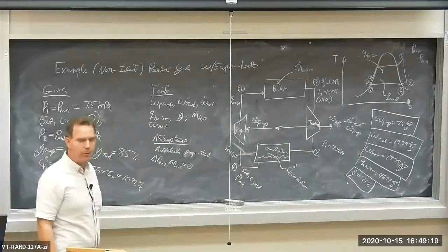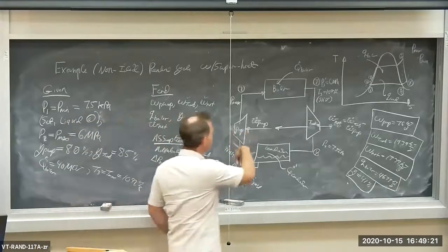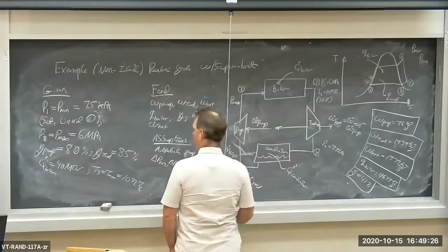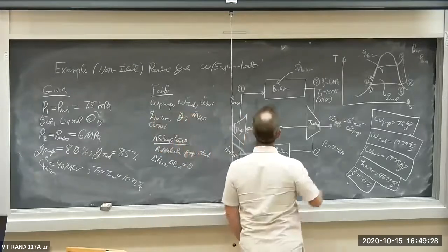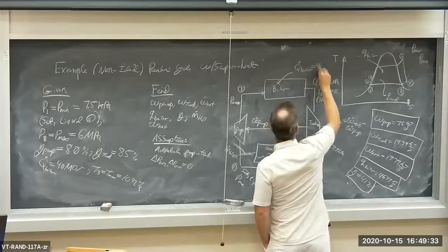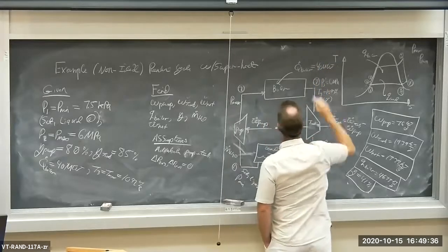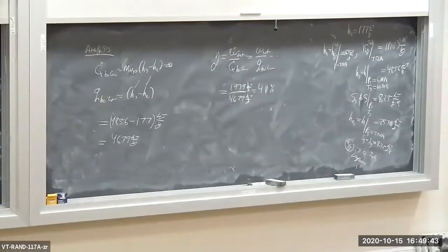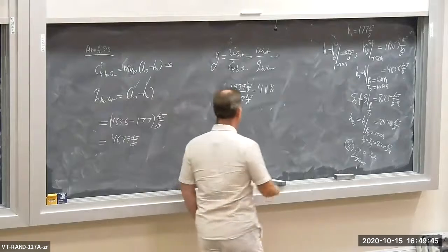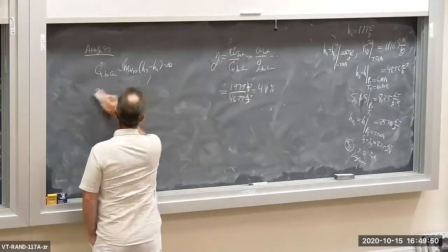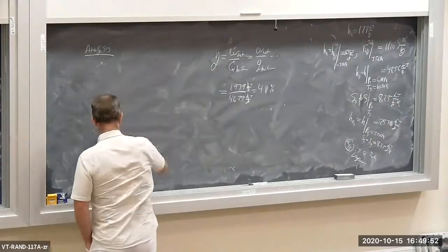Let's calculate the mass flow rate of the working fluid, the H2O, as it rolls around the system. Now, one thing I am provided here, it's simply given, but I should write it right here. The rate of heat addition to the boiler is actually 40 megawatts. Well, I know the specific heat addition, q boiler, lowercase q boiler. I know the rate of heat addition, Q dot boiler. I can immediately calculate the mass flow rate through the boiler and everywhere else.